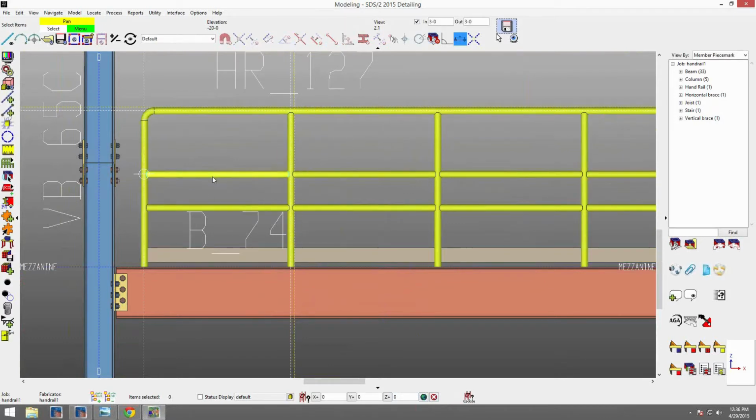Maybe I want, instead of 2 mid rails, I want 3. And also I want my spacing. So right now if I measure my mid-rail spacing from the center to the center, it's 9. Maybe I want my mid-rail spacing to be 8, and I want 3 mid-rails in there. Maybe since I have 3 mid-rails, I also want my finished floor distance to be 3 foot 8.